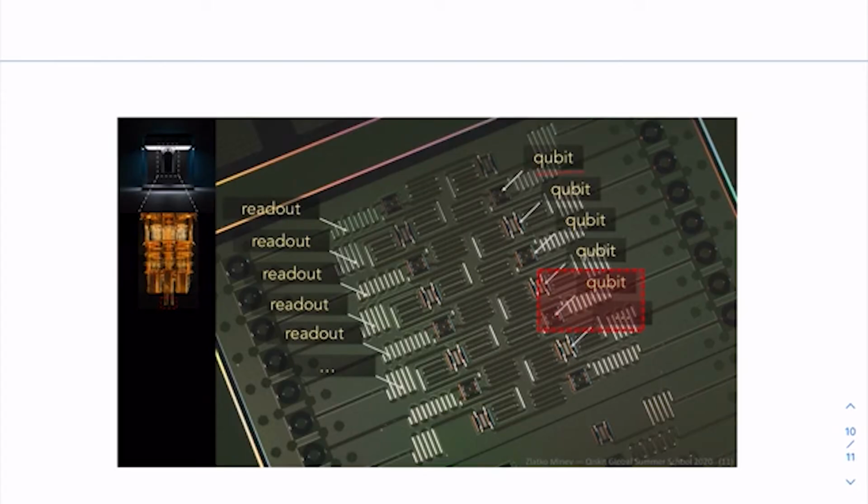These are housed in a substrate, which can be silicon, or sapphire, or some other dielectric. And apart from that, there are a number of readouts. These readouts are again superconducting coplanar waveguides, and they indicate readout resonators.